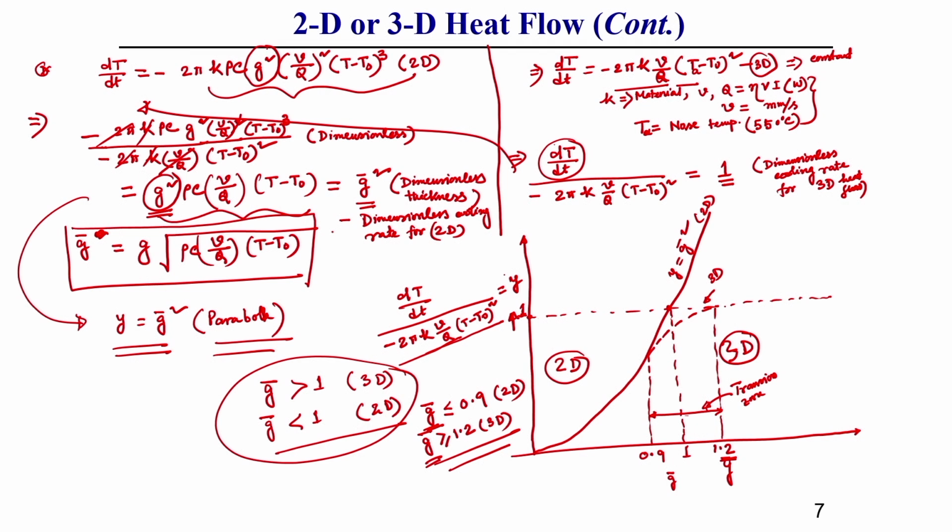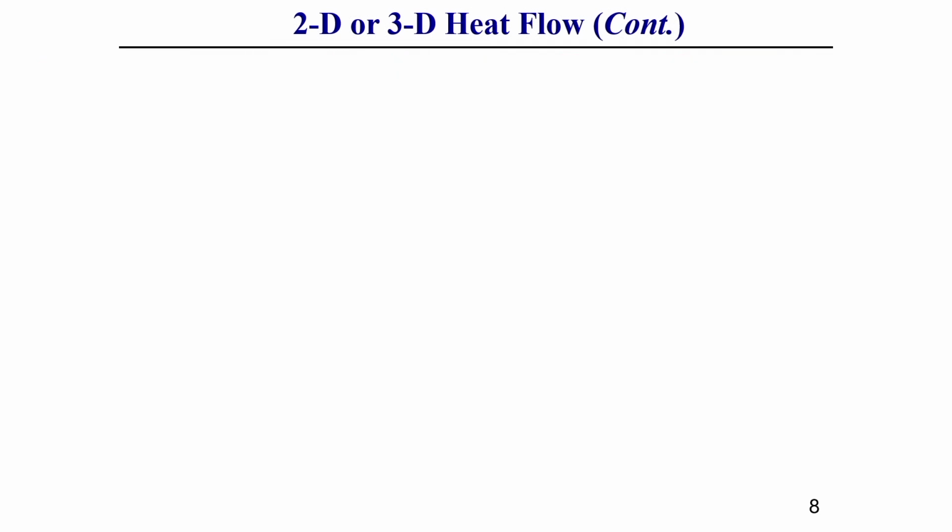Now, just before, whatever the parameter I have shown, like for submerged arc welding, generally I have shown that for a 50 millimeter thick plate, that means 50 millimeter G value with a current of 900 ampere, voltage of 27 volt, then welding speed of 0.2 meter per minute.